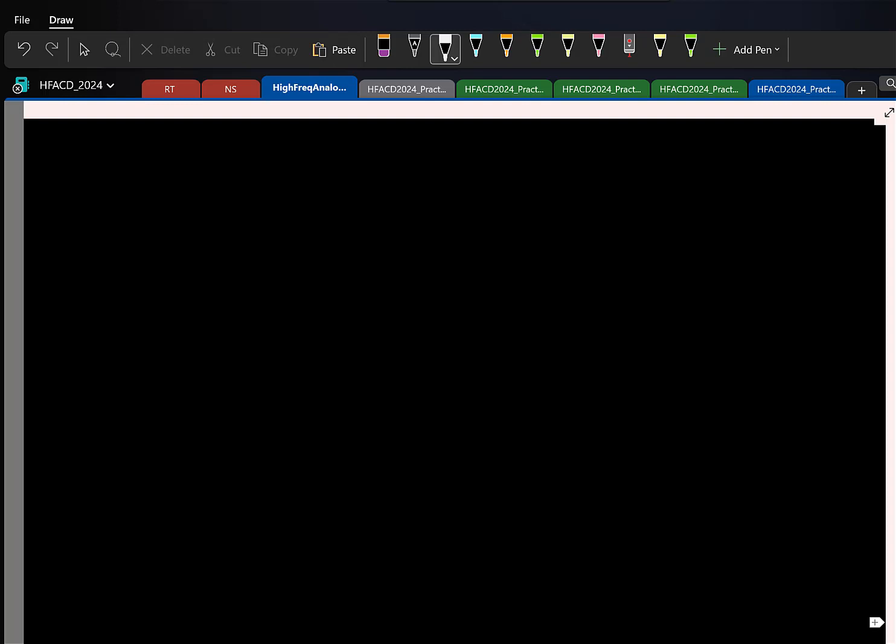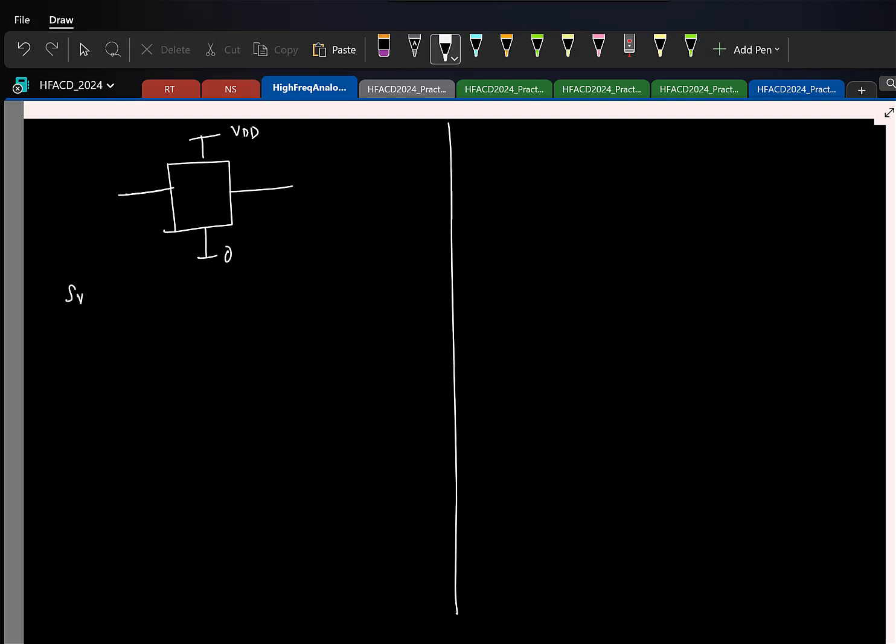So let me take this case. Let us say I take one single-ended half circuit wherein it takes only one input, one output. It operates with a supply, say VDD and 0, right? And let us say it has some power spectral density S_V(f). Now I take 2 copies of this, add common mode rejection, and make a fully differential circuit. This is the composite network. So this will also be running the same supply. Here if I find the power spectral density, it is going to be 2 times the old one, right?